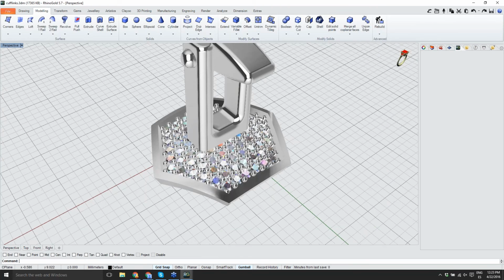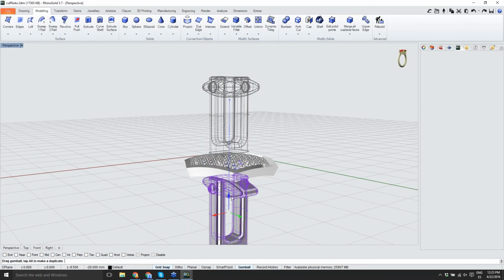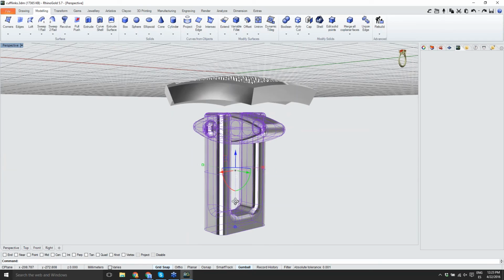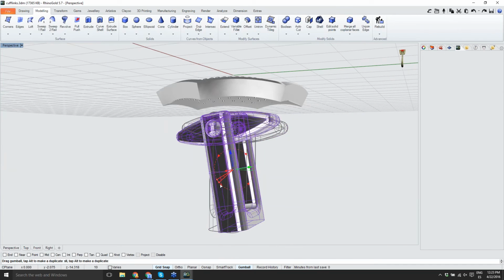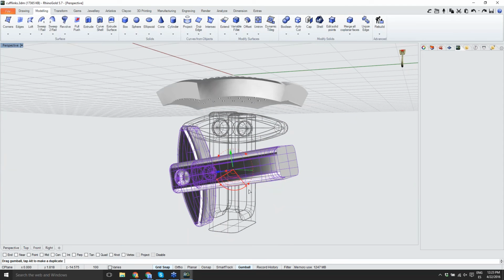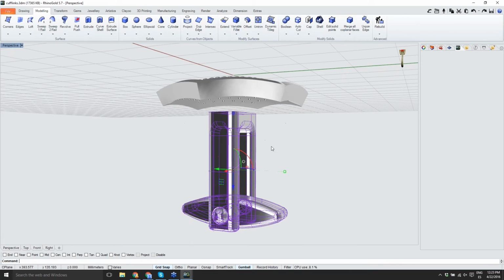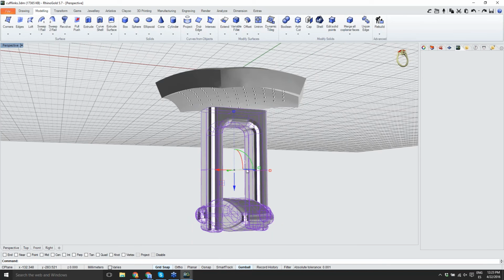So in this case, I just need to select it and adjust the position. So with the gimbal, I can drag it down, and now I can rotate also with the gimbal. In this direction. Remember, if I press Shift, it will rotate, in this case 180 degrees.